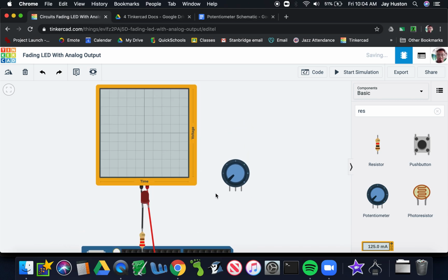That's what I want. Now, just to show you, what we would have is a constant light, right? And there's the voltage. So the voltage is on. It's giving me 5 volts because this says 10 volts, so 10 volts would be up here. This line, if the line were all the way up here, it would be a 10 volt printout, but it's halfway. So it's halfway between 0, this line, and 10, this line, so it's 5 volts. So we're getting a constant stream of 5 volts to this LED. Well done. Okay, now let's get a potentiometer in there.